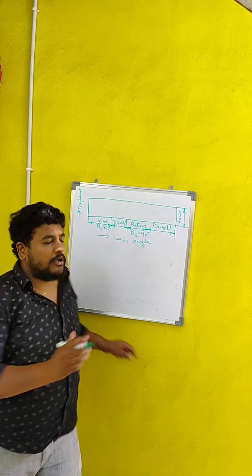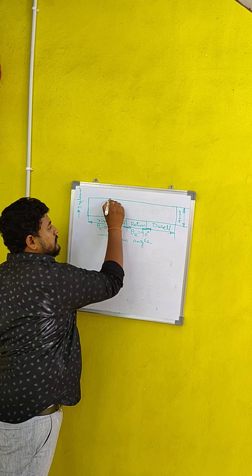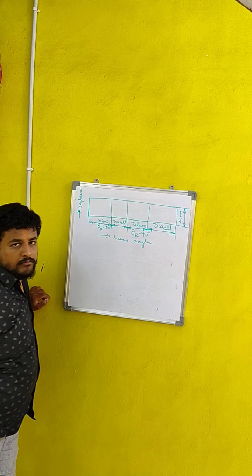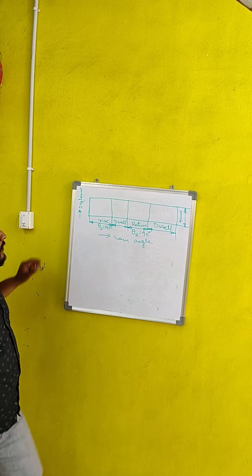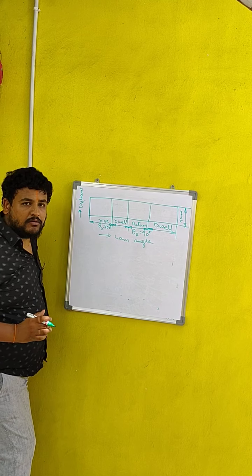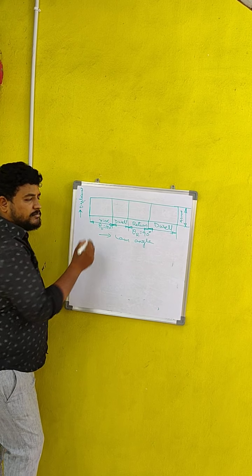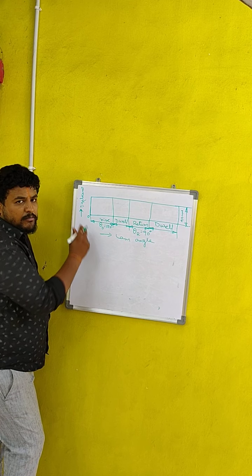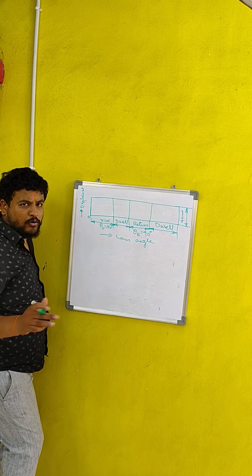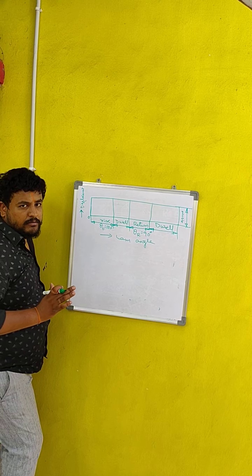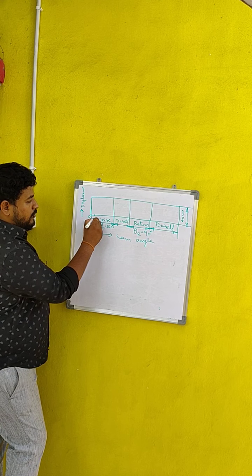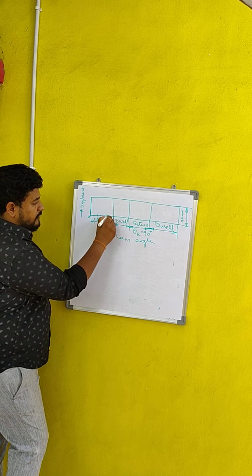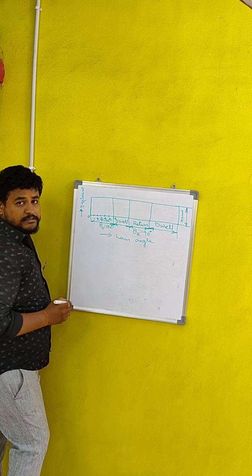Let us project all the periods, outstroke, which is called rise, dwell, and return periods. Four rectangles are obtained. Now let us divide this rise period into equal parts. Generally we make 6 equal parts, from 0 to 6, by drawing an acute angle, as you know how to divide into equal parts. 1, 2, 3, 4, 5, and this is the 6th point.